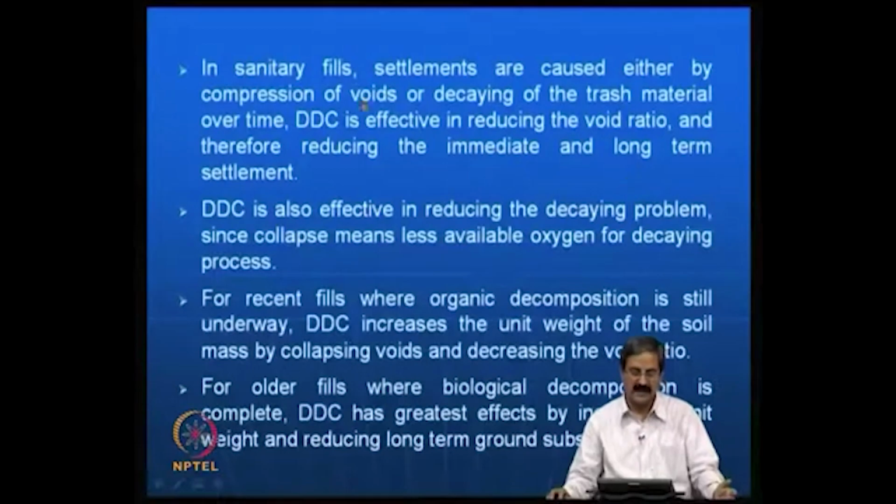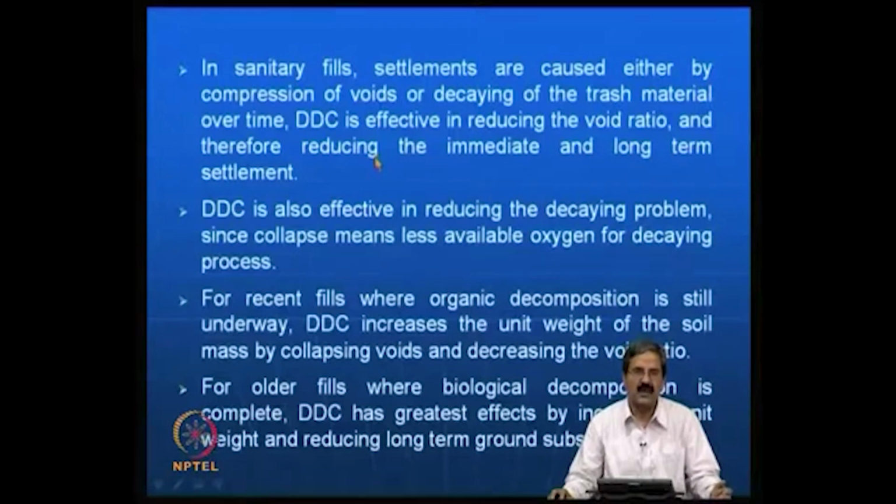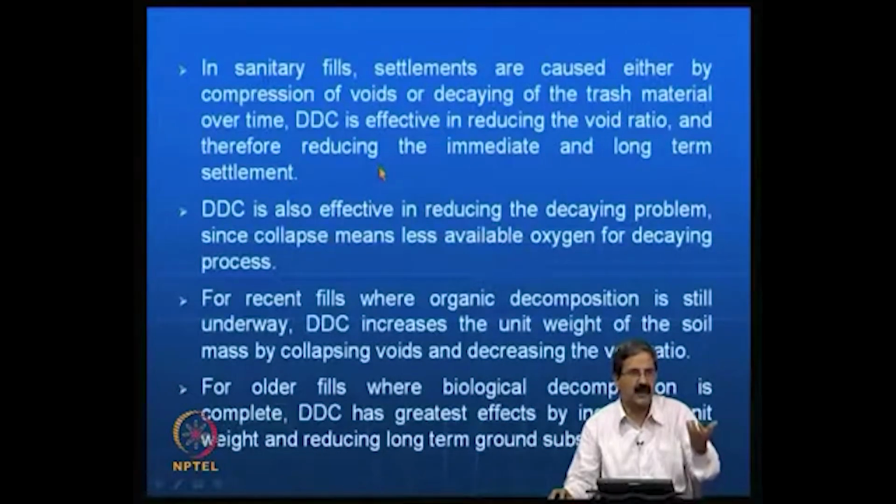In sanitary landfills or waste dumps, the settlements are caused either by compression of voids or by decaying of the trash material over time. As I just mentioned, landfills have all sorts of materials, biodegradable and non-biodegradable. For example, plastic and paper are not biodegradable, but green waste is biodegradable. In such a case it is not easy. I may say some void ratio is there, but what is this void ratio? The definition of void ratio is somewhat tricky when you have biodegradable matter present.